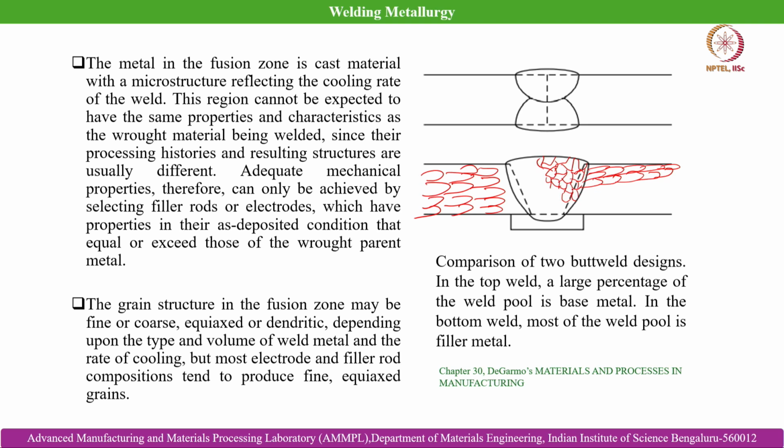So, that is why the mechanical properties also vary significantly. If we draw a center line over here, and then draw a distance, say assume that this is the distance d and this is the strength sigma, then the variation of strength depends mostly on whether it is a pure metal or an alloy that is experiencing the fusion welding process.